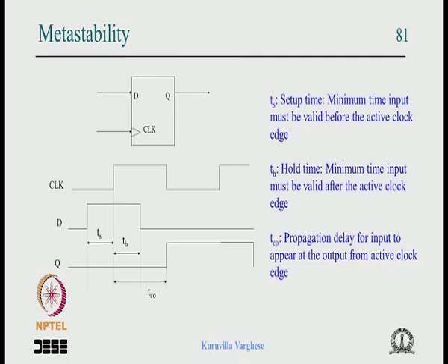Now let us come to another part. We have discussed the topic metastability. Like for a flip flop to latch or to register the input data to the output, the input has to specify some timing with respect to the clock edge. That means when the clock edge comes, the data has to be set up sometime before it, and after the clock edge it should be held on for some more time, so that the value at this point gets faithfully copied or transferred to the output, okay.